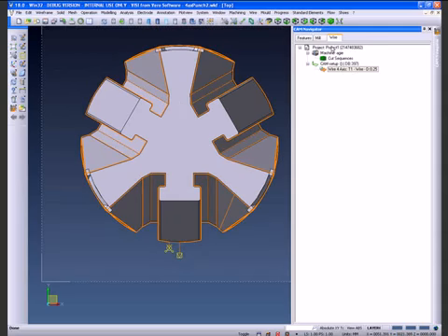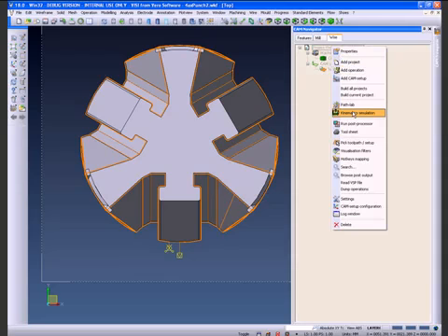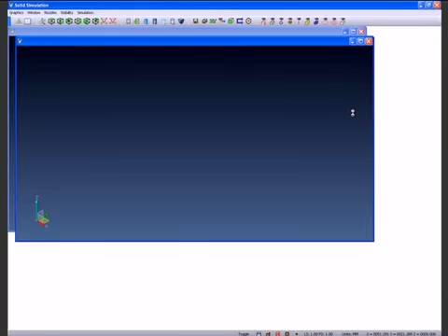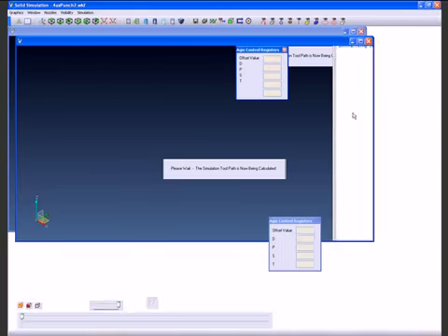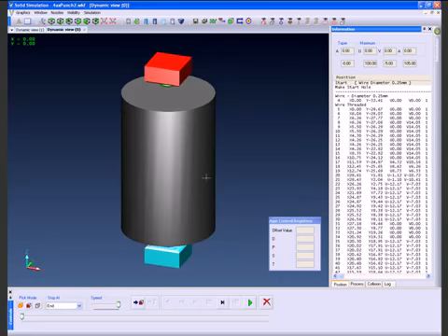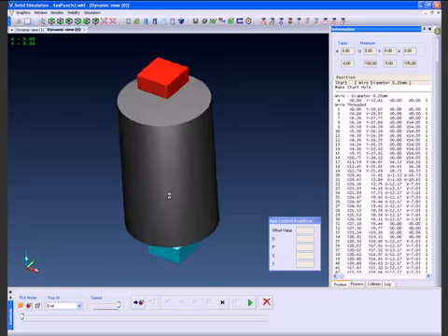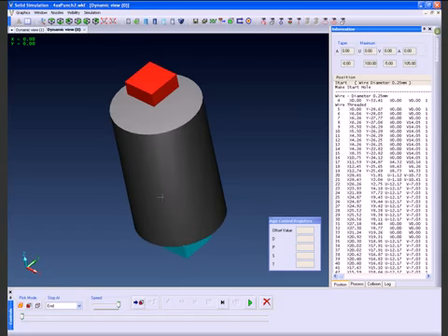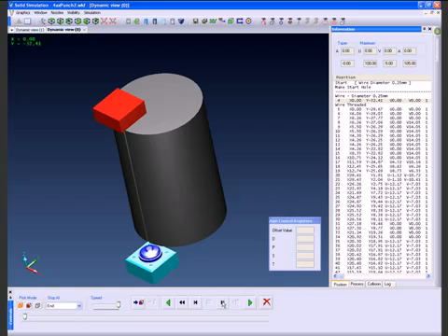We can go to the project and actually then call on the solid simulation or the kinematic simulation. This reads in the solid stock as well as the piece that we're going to wire, and it uses both of those to generate the solid simulation. You will notice that the top and bottom nozzles are 5 mm higher than the stock, which was determined in the previous dialog. Let's now run the simulation.